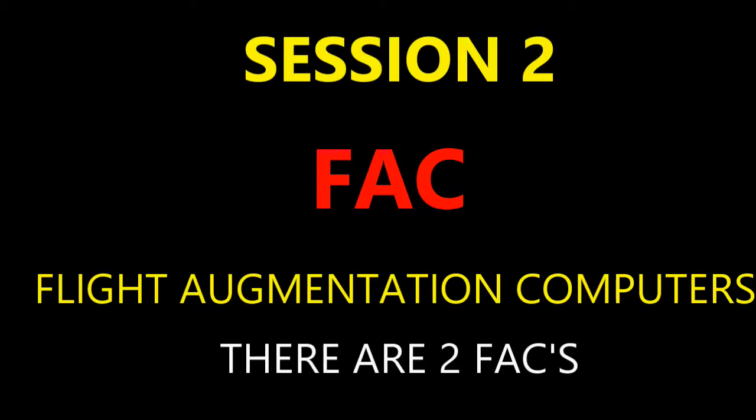If it goes below a certain energy, then there's going to be a warning sent to the ECAM. Your excessive angle of attack, that's what's called an alpha floor, just to let you know right now. But you're going to hear that later on. I might as well get it in your head a little bit right now: that's what an alpha floor is, that there's too much angle of attack. That's what we don't want.